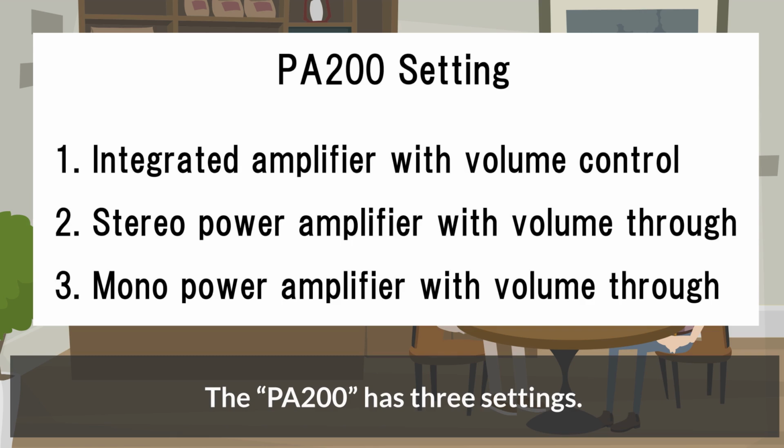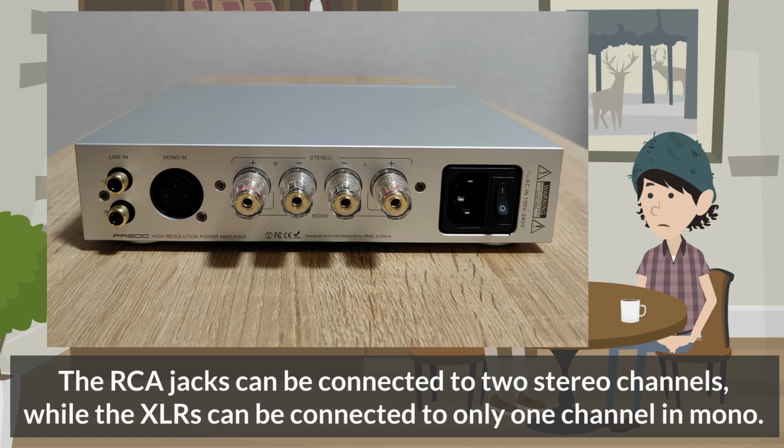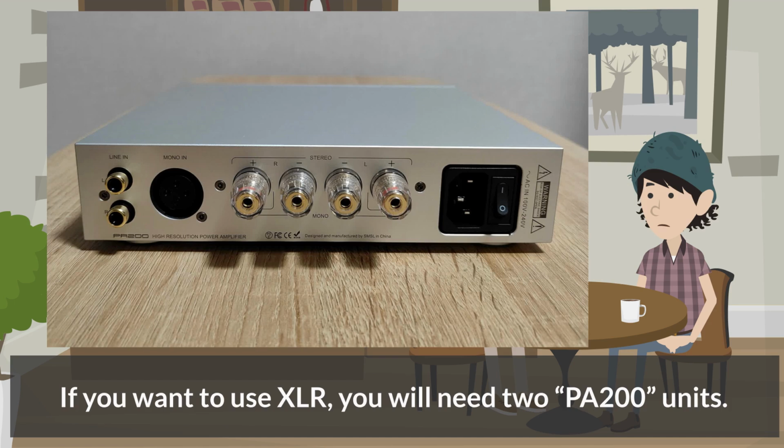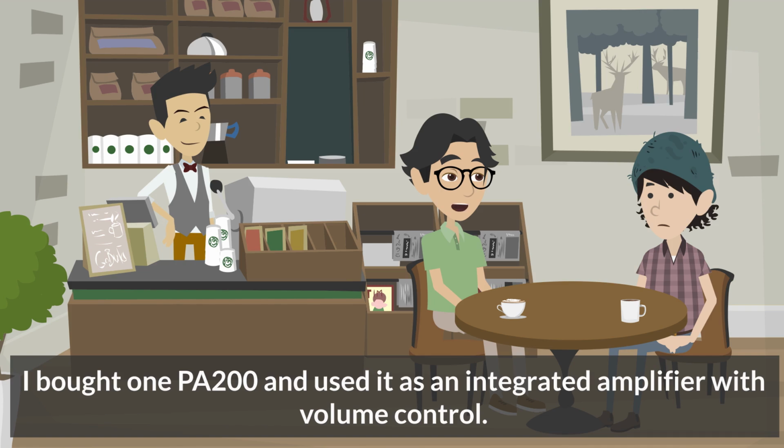The PA200 has three settings. 1. Integrated amplifier with volume control. 2. Stereo power amplifier with volume through. 3. Mono power amplifier with volume through. The RCA jacks can be connected to 2 stereo channels, while the XLRs can be connected to only 1 channel in mono. If you want to use XLR, you will need 2 PA200 units. How did you use it? I bought one PA200 and used it as an integrated amplifier with volume control.